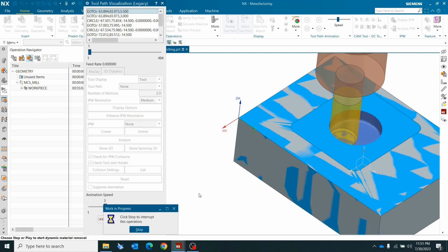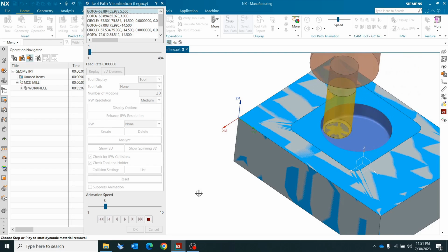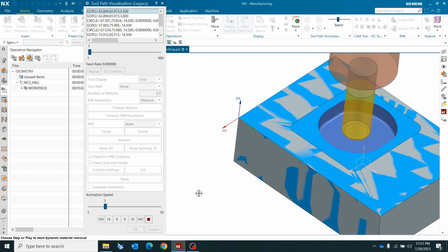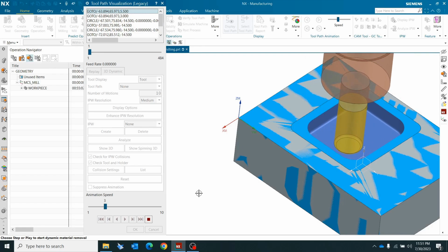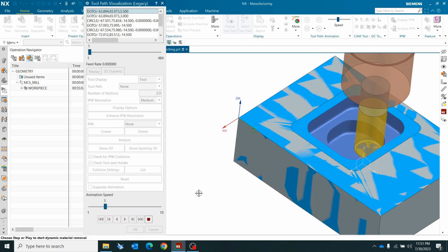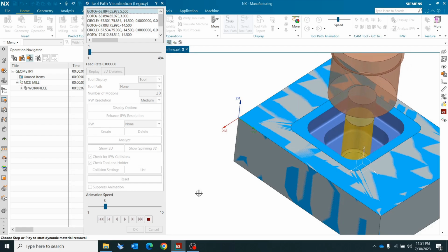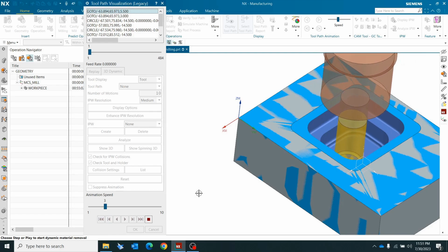So now I have given 30%. When it reaches 30% of flute length, means 15 mm it is going, and then after reaching all the region, then while coming back it will remove every time 3 mm. First it will go to the bottom region. Previously whatever we have seen, similar to that it will go. So once it reaches that particular region, it will start removing material while coming in the backward direction. You may see 3 mm, 3 mm, every 3 mm it will try to remove.